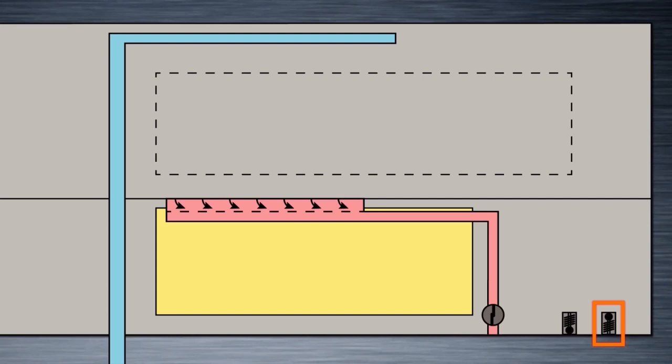If the outflow valve were to fail, air would start collecting within the cabin and differential pressure would increase. When this occurs, the positive pressure relief valve bleeds cabin air overboard so that a maximum pressure differential of 9.1 psi is restored. Once the conditions are normal, the positive relief valve closes.